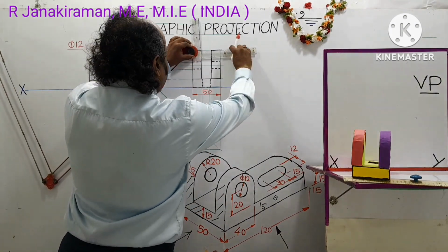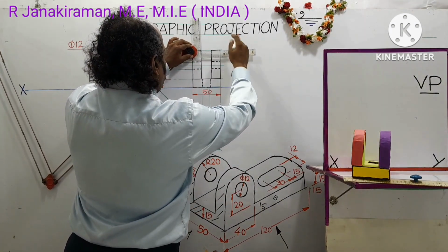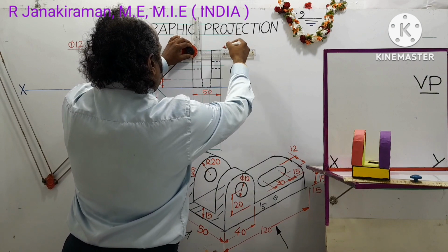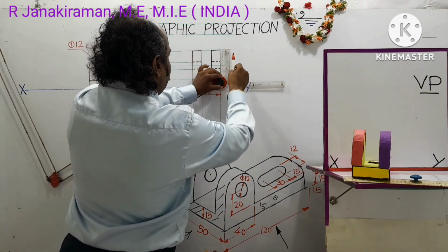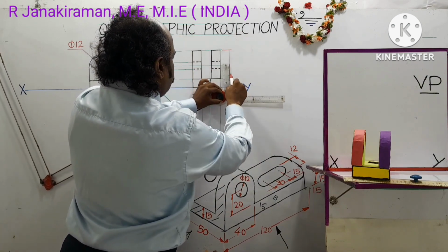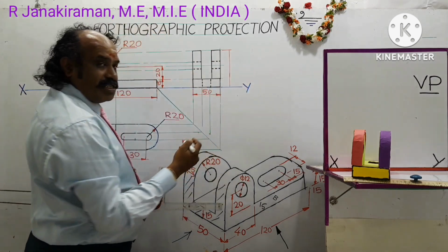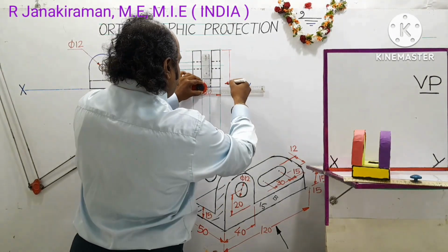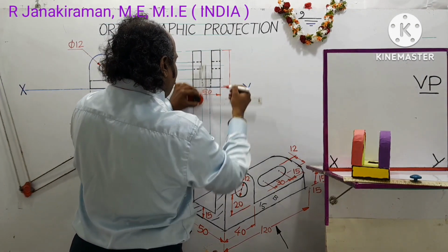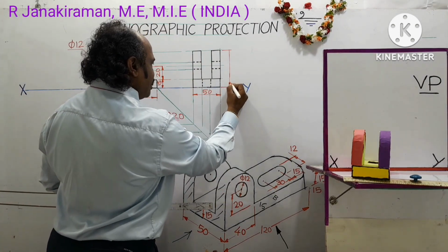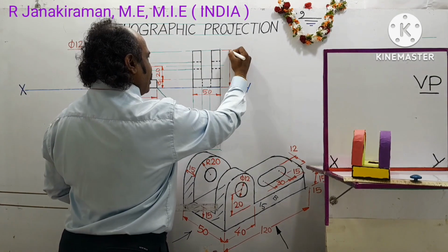Draw the extension line. Next, draw the dimension line and put arrowheads. The writing work and all should be carried out using an HB pencil, so that it appears dark. One who reads the diagram must be able to visualize and understand the size provided in the diagram.